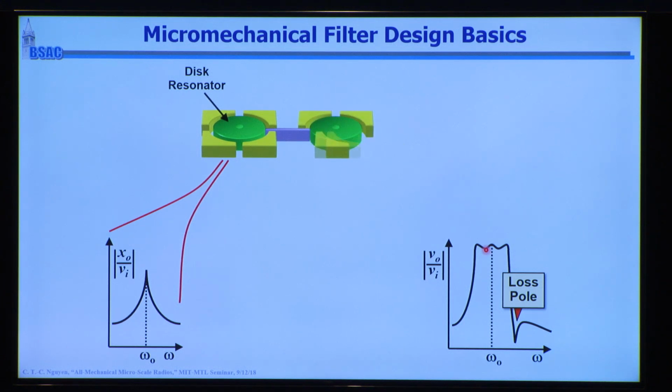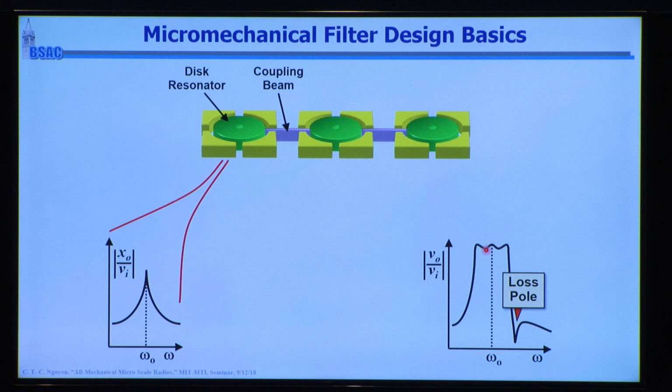Well, you make a circuit out of this. The same thing you do in electronics, you do in mechanics, except you make the circuit out of these mechanical disc resonators, and you link them together mechanically, not electrically. So you're really linking the velocity of this one to the velocity of that one to the velocity of that one, transmitting them down these mechanical lines. This is great because now you are immune to parasitic capacitance and other electronics going to the substrate. So you basically convert everything to the mechanical domain here. You process in the mechanical domain, and then you reconvert to electrical if you have electrical stages after this. You'll see later on, I'm not even going to have electrical stages after this. This is going to be all mechanical. It'll be a much simpler mechanical circuit. But anyway, this is your filter.